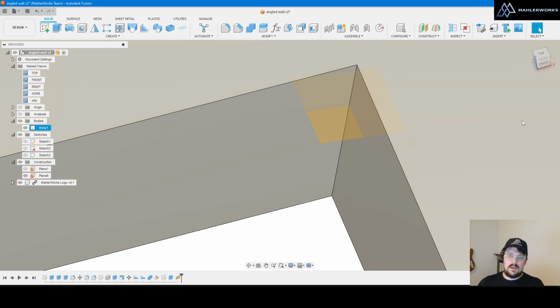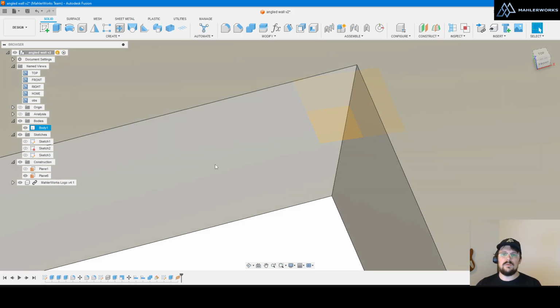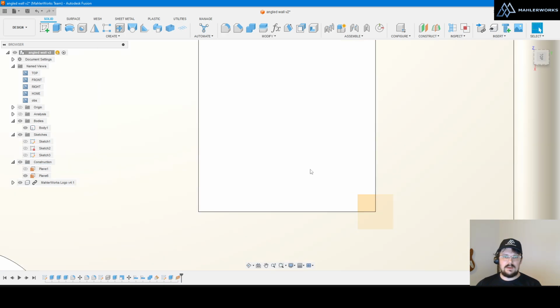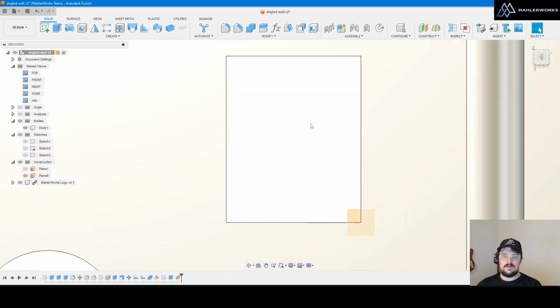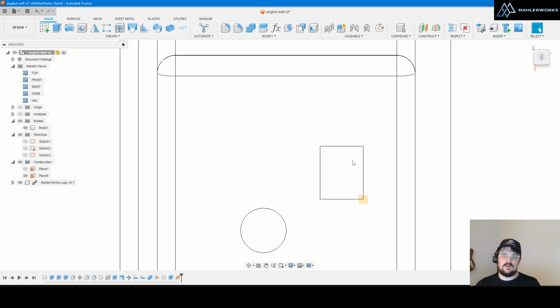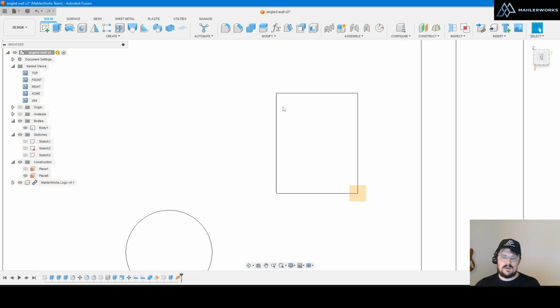I'll just say OK wherever it is. Remember, I'm only trying to look directly down this hole. I'm going to click this face and then say look at, and it rotated and oriented on its own. But there we go. I'm now looking straight down the square, and if I do a wireframe view, I can see that my walls are completely perpendicular to my view.